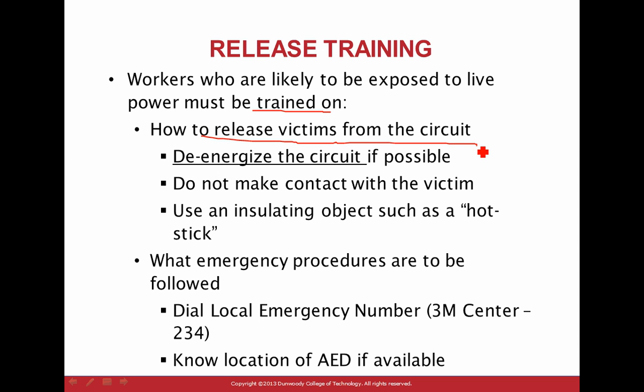We'll talk about what happens if somebody is being electrocuted. Would you sit there and watch him turn into a hot dog, or what would you do? De-energize. The first thing you need to do is look around. Where is the closest disconnect switch so you can slam that thing, or the closest emergency shutdown button? That's part of the training they do for new equipment. When you buy new equipment, the first thing to ask is where's the emergency button so you can shut it down and save the rest of his hand. So, releasing the victim: de-energize the circuit if possible.